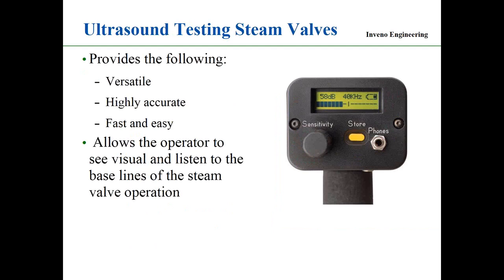The next thing is that setting up the ultrasonic units is very versatile, highly accurate, fast, and easy. The high frequency ultrasound units give me a display of the ultrasound that I'm picking up, which is a visual, and it also gives the operator of the unit the ability to hear that sound. The high frequency ultrasound is heterodyned into an audible sound, so you can listen through a headset. So you get two things: a visual, and you also get to hear the valve if it's leaking through.